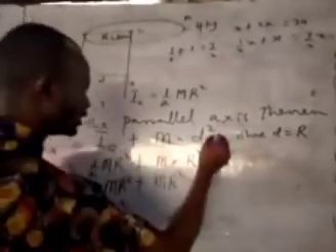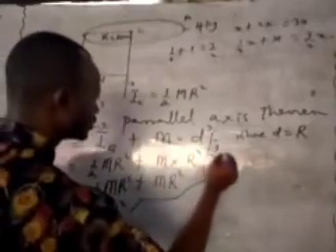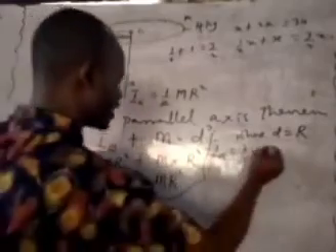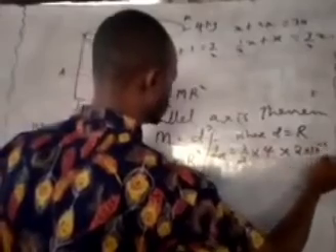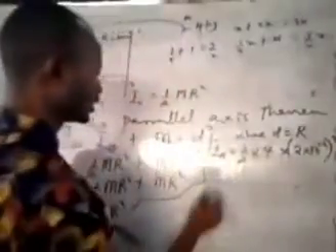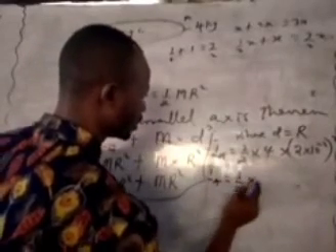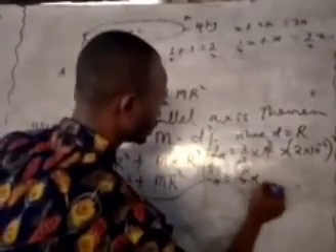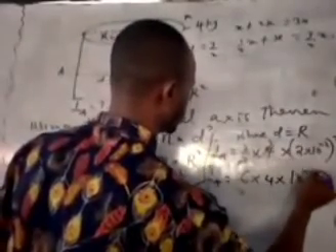So the inertia I sub A will now be equal to 3/2 times the value of the mass, 4, times R, which is 2 times 10⁻² meters, squared. So the inertia about A will be equal to 3/2 times 4, and these 2 can cancel this 4, that becomes 2. 3/2 times 4 is 6, times, when you take the square of this, 2 squared gives us 4 times 10⁻⁴.